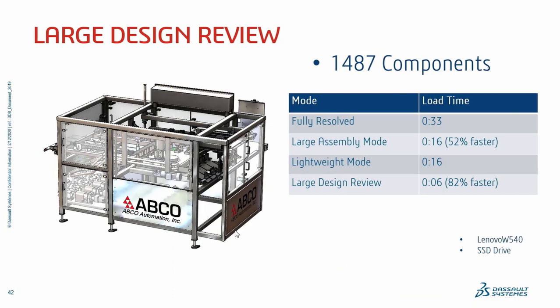This is an example where this assembly has 1487 components. Okay, in a fully resolved mode it takes 33 seconds. In the large assembly mode it takes 16 seconds, and lightweight mode 16, and large design review it takes only 6 seconds to load this assembly into the software. So that is how the opening time will reduce.